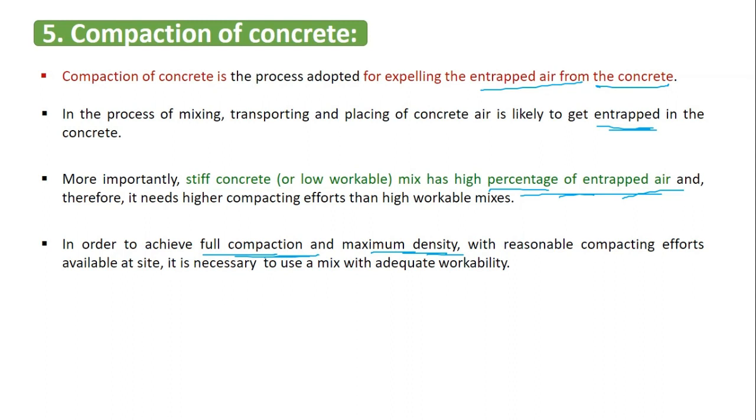But remember, the workability of the concrete influences the compaction that you can achieve. If a concrete is less workable, compaction becomes hard and difficult. When the workability of the concrete is high, the removal of air is very easy. While designing the concrete, you need to decide what percentage of compaction you need to achieve.